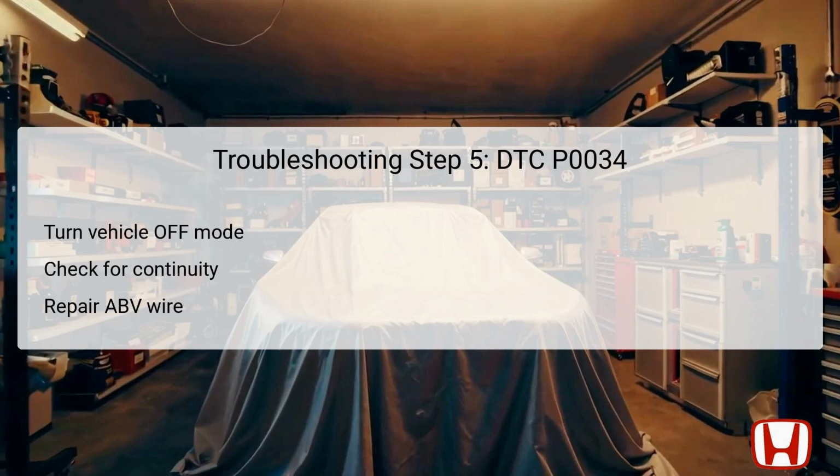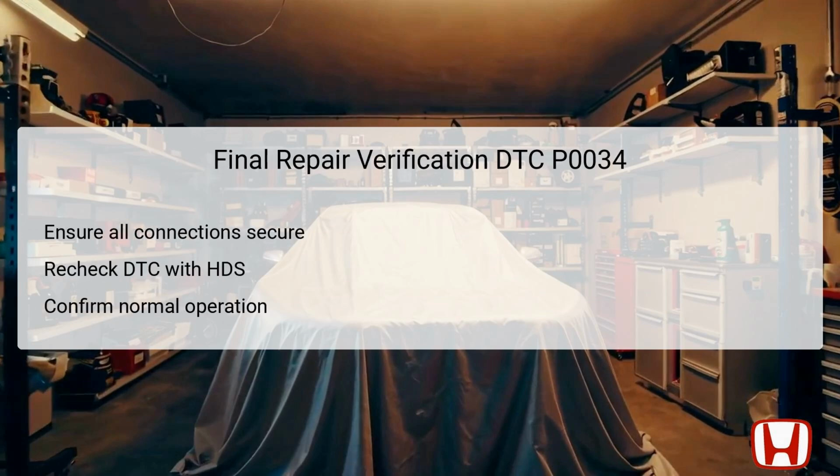If continuity exists, this confirms that the ABV wire is operational. If no continuity is detected, further inspection should be conducted on this line, and any shorts in the ABV wire connecting the PCM to the turbocharger bypass control solenoid valve need resolution. If issues persist, check for service bulletins related to this DTC or consider substituting with a known good PCM to rule out module malfunction. Once all troubleshooting steps have been meticulously followed, it is essential to conduct a final verification to ascertain that the repairs were successful.